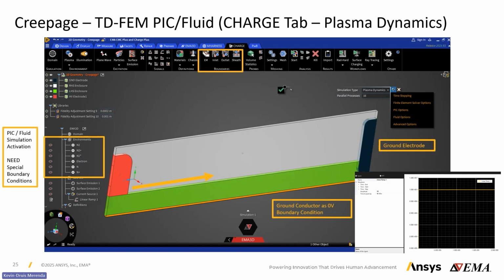So let's go back to this model here. We looked at a flashover simulation. We can actually run a flashover simulation using the PIC solver and the fluid solver. What I did here is I effectively took the nanosecond pulse tutorial that I presented earlier for air. You can see the environments that are generated here. For each of these species, you have to specify what kinematic model you want to use to track them, either the PIC or the fluid, and it's selected within the system. You can also select which type of electromagnetic plasma model you want to use, whether the conductivity or the space charge model.